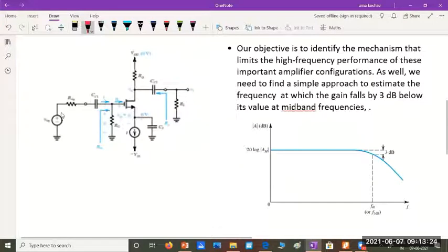Let's consider a common source amplifier as shown, where we have the input signal generator Vsig with its internal resistance Rsig, and CC1 represents the input coupling capacitance, Rg is the biasing resistor, and this is our MOSFET. Here we have used constant current biasing, which you haven't studied actually, but that's the one considered here, where a constant current source will be present in the source region, connected to the negative of a DC power supply, minus VSS.